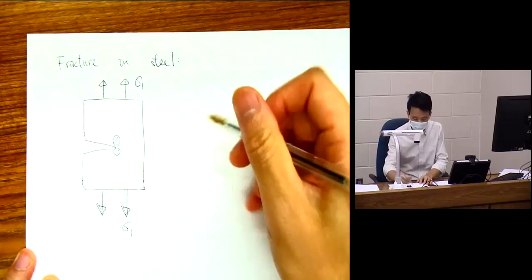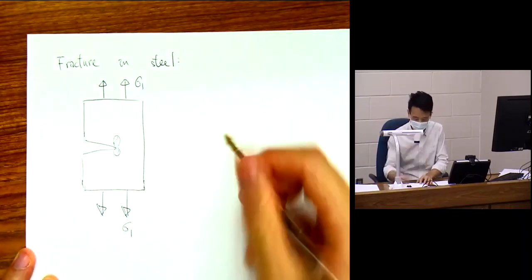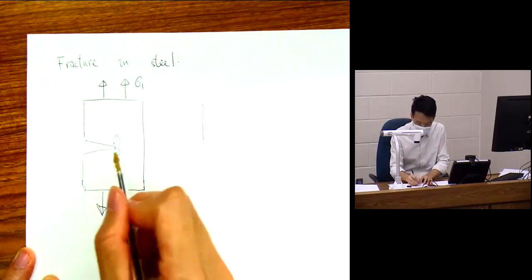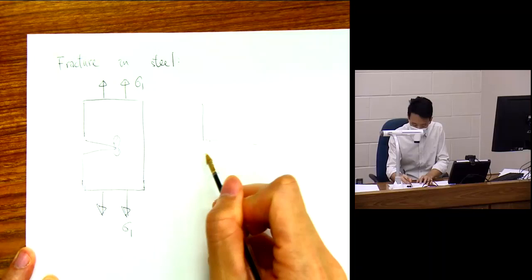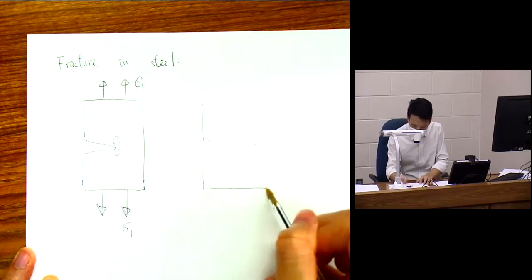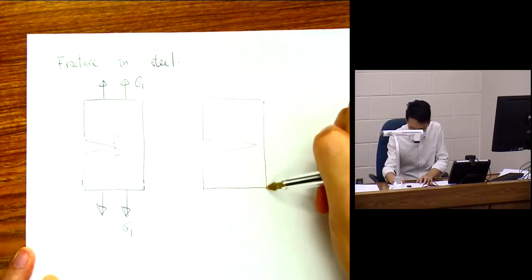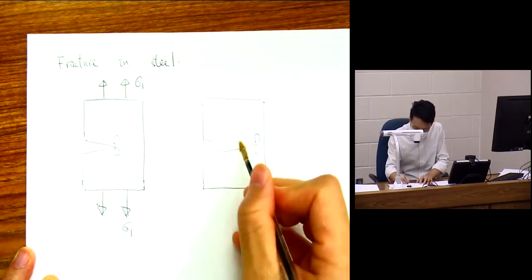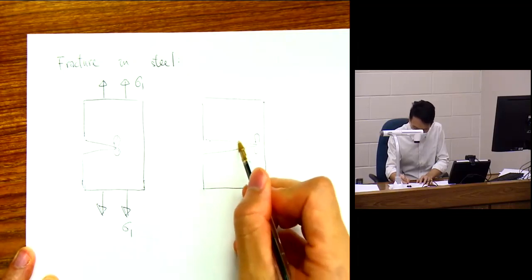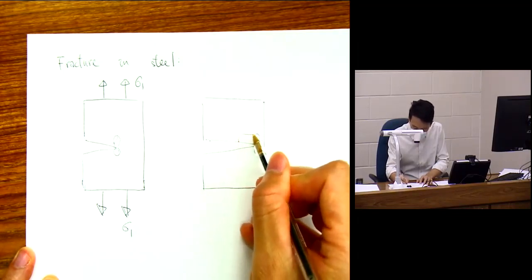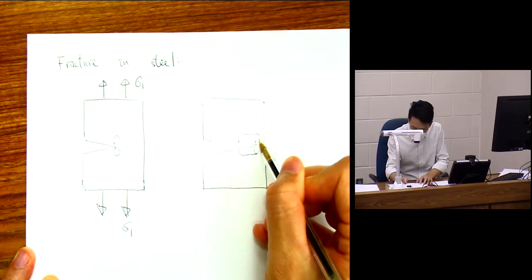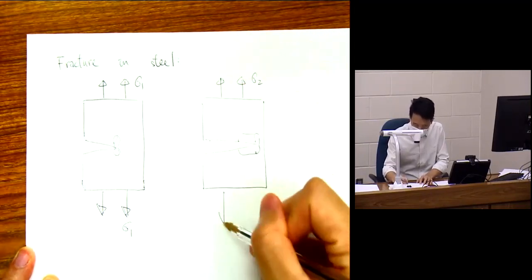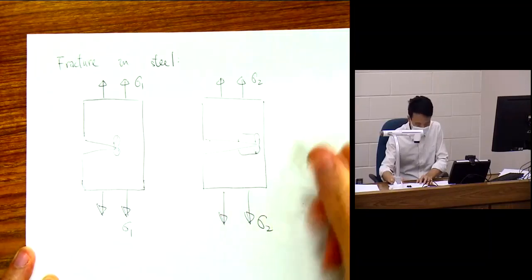So you increase the stress, and now the crack starts to advance. So now the crack length is slightly longer. But the plastic zone originally is around here. A different stress, higher stress, sigma 2.